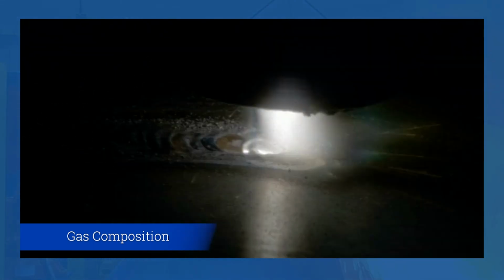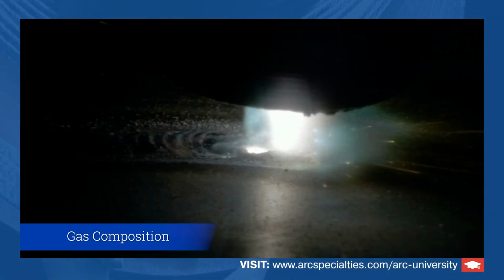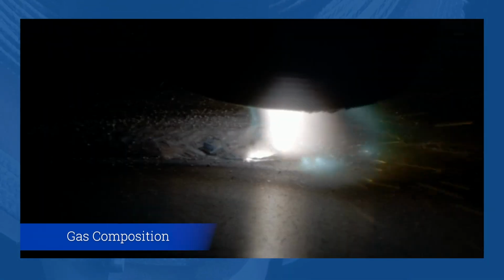Let's talk about gas composition. What you see here is a pure argon shielding gas. You see the edges of the welds are not wetting out. That's because we have nothing to reduce the oxides. There's no flux, there's no hydrogen. Here we change the gas composition. We're running a shielding gas with 5% hydrogen.